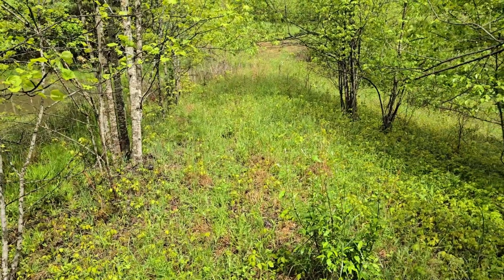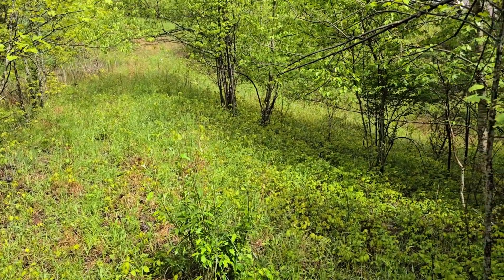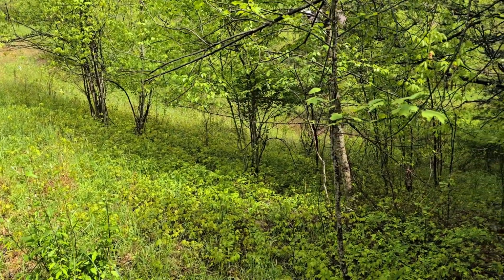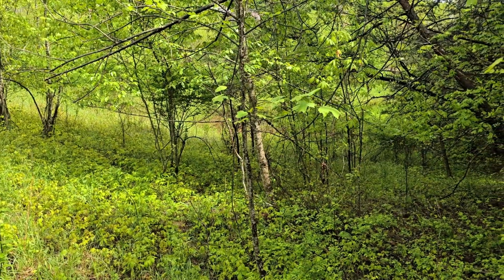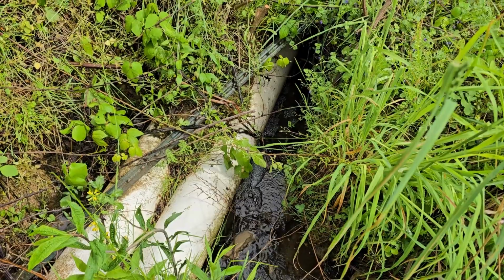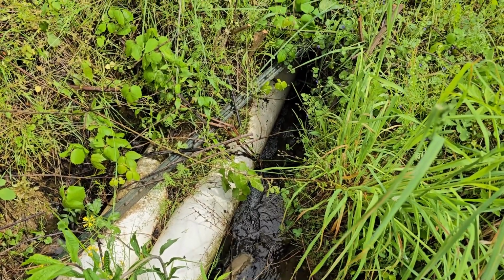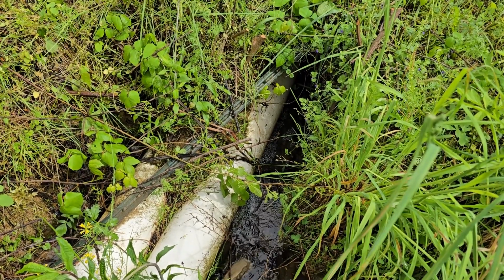The many trees and shrubs with thorns that were growing on the dam made it challenging to inspect the dam for holes and leaks. Fortunately, I did not find any muskrat or beaver burrows in the dam. The dam was built without a spillway. I found these 6-inch diameter pipes with water flowing under them on top of the dam. The stream was flowing under the pipes and was carving a ditch through the top of the dam.